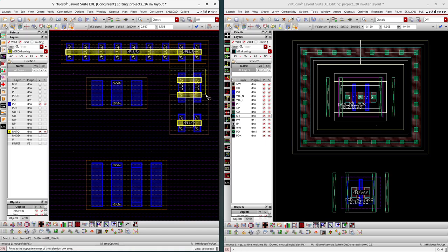So we can consider this as a device. Instead of calling it a guard ring, here we have OD, poly and all the layers. So we can say this is also a device, but it is acting as a dummy device. It is a kind of device which is creating contact. This is also acting as a guard ring, and it is kind of a device only, because poly is also there, OD is also there, and M1 is also there.